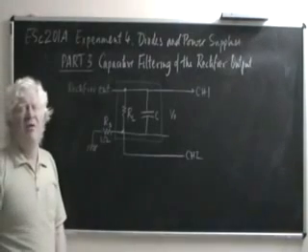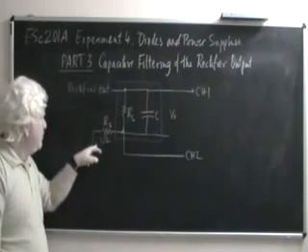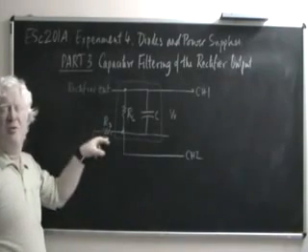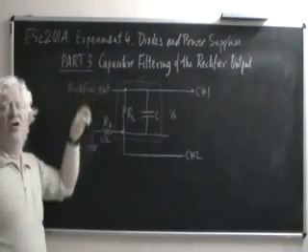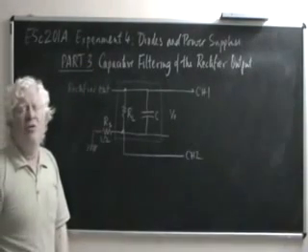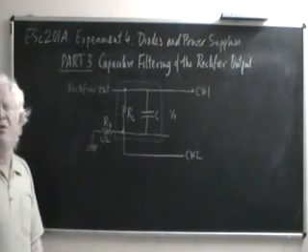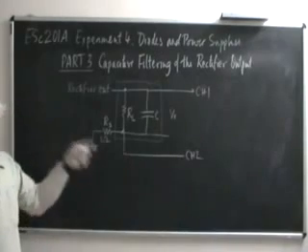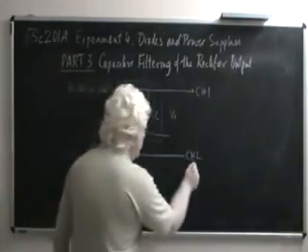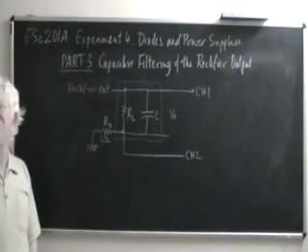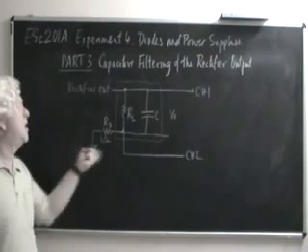The last time we were trying to measure current, which was when we were trying to plot the diode characteristics, we put the series resistance meant for voltage measurement on the source side, not on the ground side. And therefore, measuring the current by using the proportionate voltage developed across the resistor required a difference amplifier. Here we don't need to do that, because one end of RS is already at ground, so channel 2 that's connected to this will directly give you the voltage across RS with respect to the ground, and that voltage will be proportional to the current that's passing through.